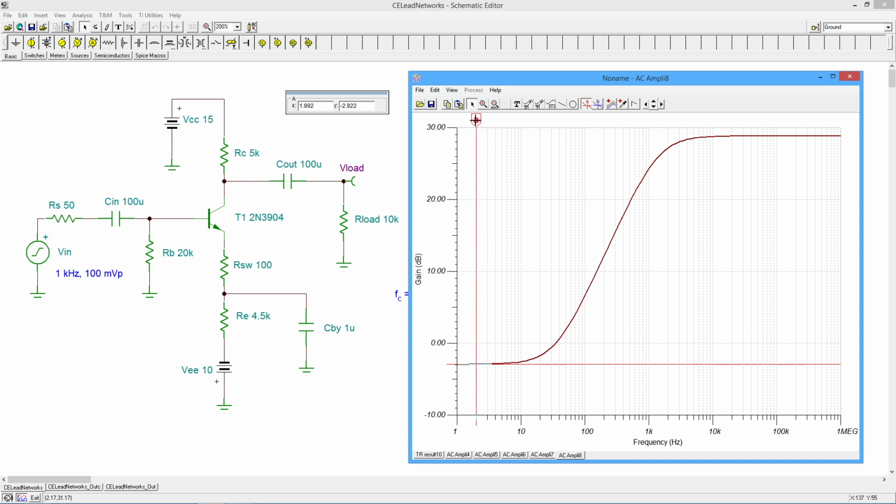But in any case, we're sitting down at minus 2.9. If I push it all the way down here, it's virtually minus 3. So I'm looking at 3 decibels above this point. All right, so minus 3, we go up 3. I'm looking for about where it hits 0. And here we are somewhere around 34, 35 hertz, right in that region. So again, that's where the bypass capacitor winds up equaling RE, and the bypassing no longer exists. It doesn't bypass anymore. Okay?